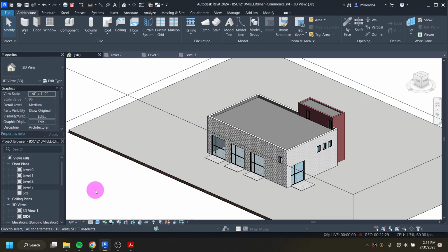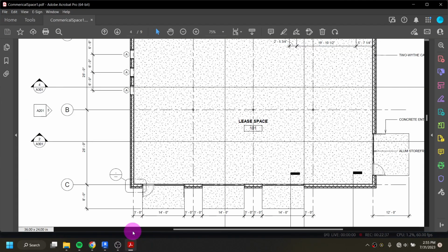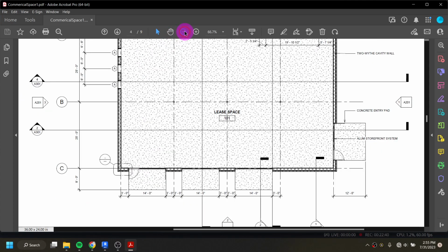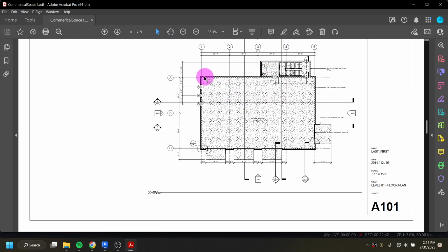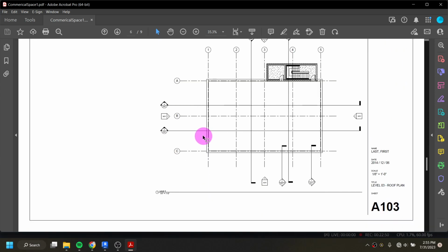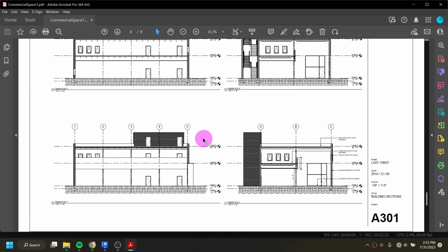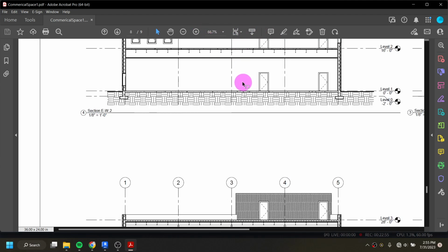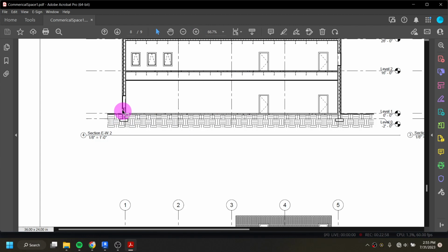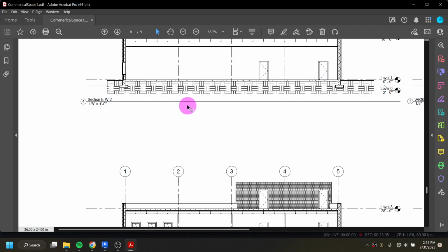Now, Revit has automatic levels and presets for where floor plan cuts are being made. If you remember back to the beginning of the course and I talked about floor plans and how this cut is determined, I would say that it's usually 4 feet above the top of the floor. So if we go look at like a section here, that this floor plan cut, it's measuring 4 feet up and then slicing the building open to look at the floor plan. And that's where we can see things like doors and windows and their locations.